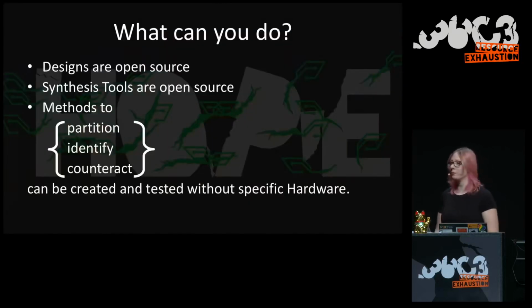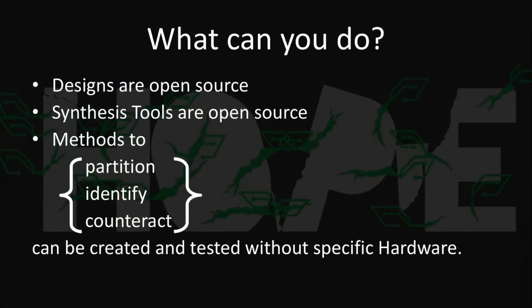What can you do? Those two main problems I mentioned right now, the partitioning and the identification, you don't need any kind of specific hardware for that. You don't need any kind of specific tools for that. Any kind of designs you can use here are open source. So I mentioned OpenCores and LibreCores. Feel free to download everything there. Feel free to synthesize everything there with wonderful open source tools you can get. So Yosys, Qflow, all that kind of stuff. So that's something you can do.